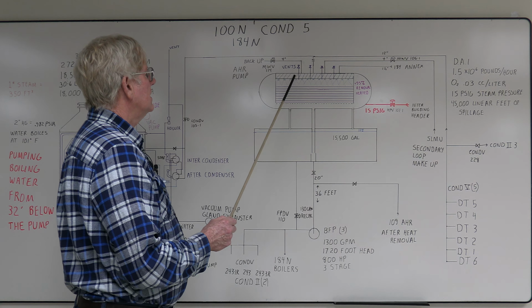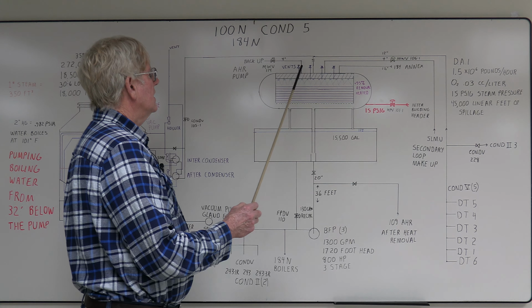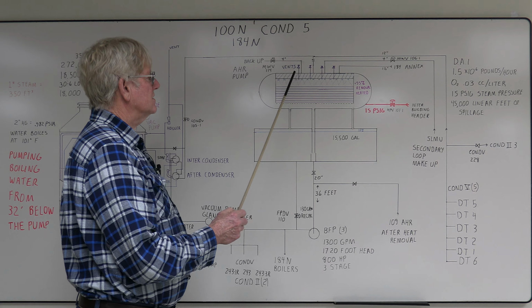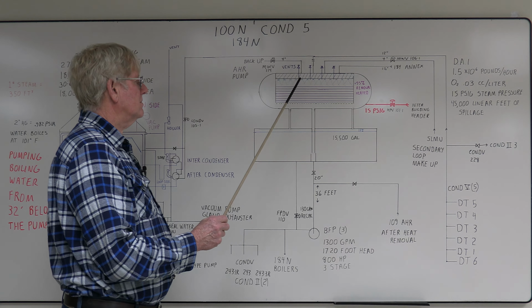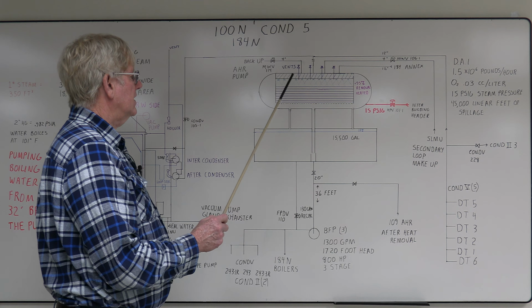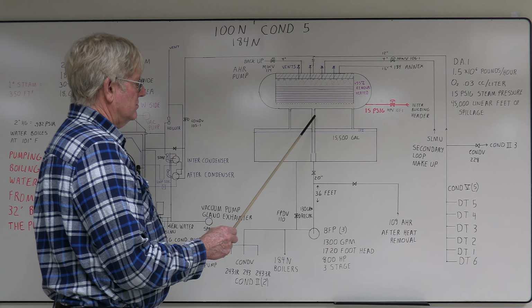The drawings show there was a vent condenser. I really don't have anything on them. I know a lot of them did. You want just a slight amount of steam to come out of the vents, not blowing. If you don't have any steam coming out at all, you're probably not venting, and you'd also have high O2. The O2 is checked down here.